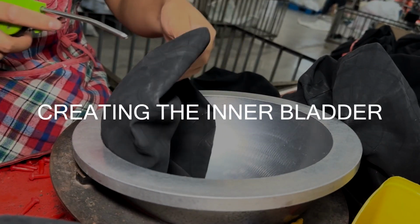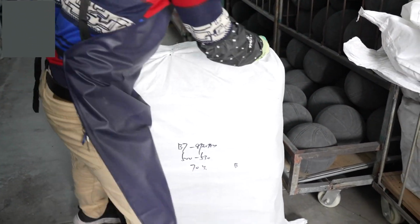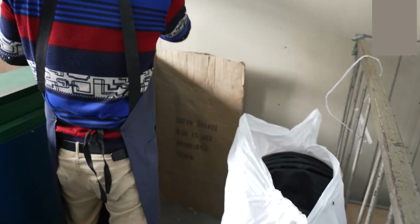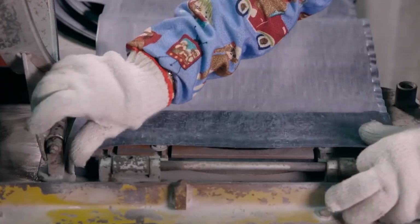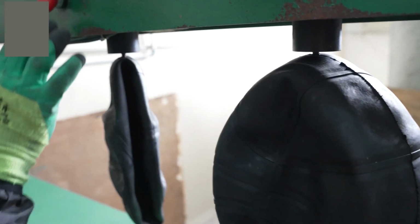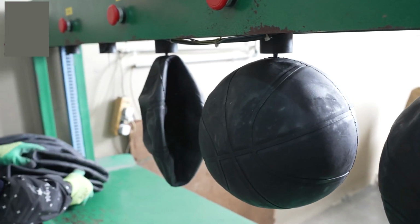Phase 1. Creating the inner bladder. The inner bladder forms the core of the basketball. It is made from black butyl rubber, which is known for its excellent air retention properties, providing the necessary bounce for the ball. The butyl rubber is melted and molded into flat panels. These panels are then joined to form the shape of a basketball. This step requires precision to ensure the bladder is seamless and can hold air without leaking.